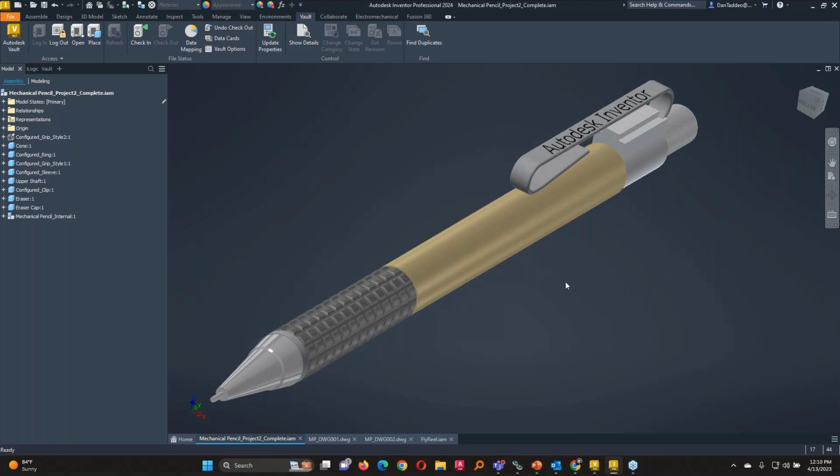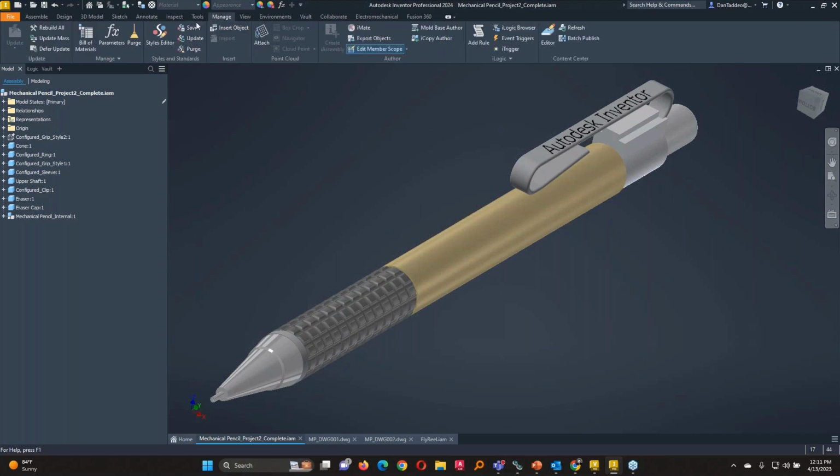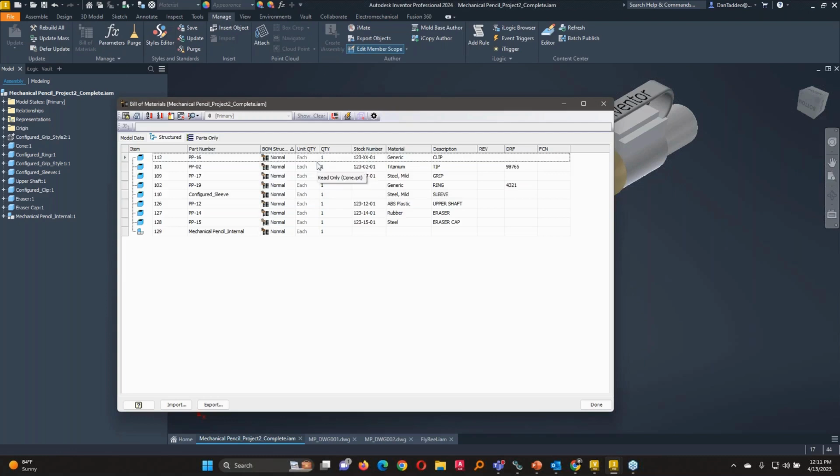Say I'm working with a manufacturer like John Deere, and we've got the engine components, the alternator, the water pump, the fuel pump, and things like that. And sometimes with that packaging, we might include additional parts, additional bolts or something like that. Maybe it's grease packets, right? How do we model grease packets? Well, we don't. What we do within the bill of materials is use something called a virtual component that will be a line entry in here.